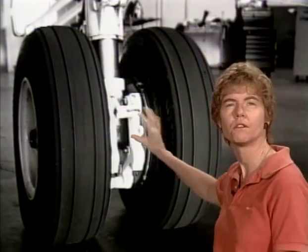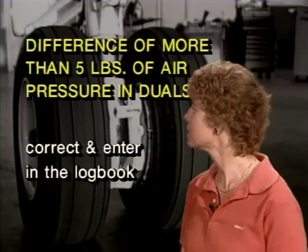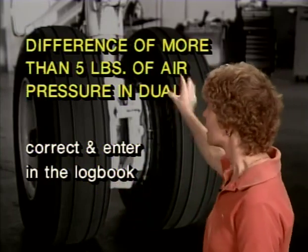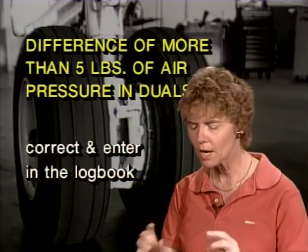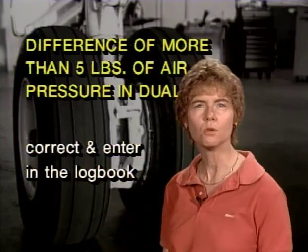Here you've got a set of duals, and you're checking the tire pressure on both of them. What if there's a difference? If the difference is more than 5 pounds of air pressure, what you do is correct the discrepancy, but then you enter it in the log book. You need to make a note of it in the log book so that an eye can be kept on those two tires and see if there's some sort of recurring, continuing problem. Go ahead and correct it, but make a note in the log book if there's a difference of more than 5 pounds of air pressure in the duals.